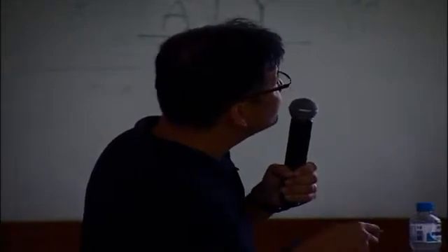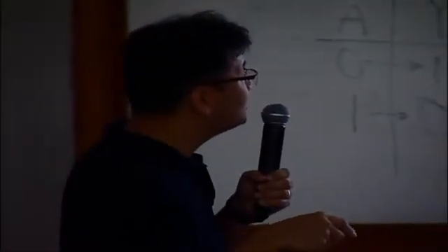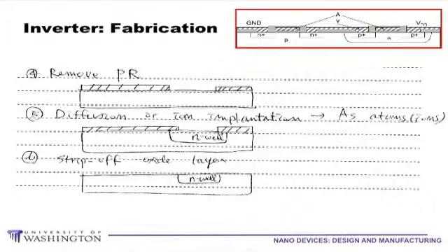So what we will do is deposit gate oxide and then a polysilicon layer on top, and then do the lithography and then etching. Then we can create this structure. Now these two structures correspond to this structure. Okay? So we use the second lithography. If the yield of one lithography step is 90%, then after the second one, we will have about 80%, right?